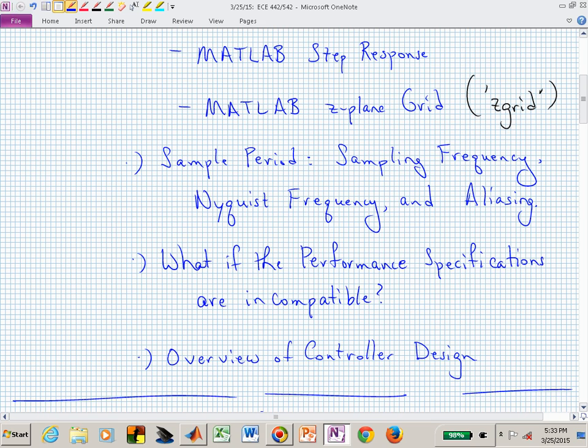And if we have frequencies above the Nyquist, those frequencies will now alias back to frequencies between DC and the Nyquist frequency, and it's nice to know that is possible, and that's why we want to sample fast enough to avoid anything like that happening.